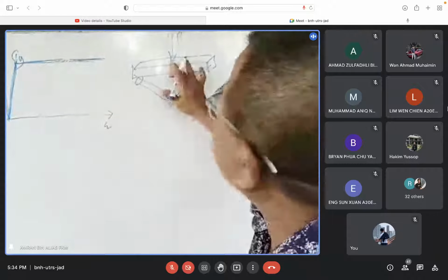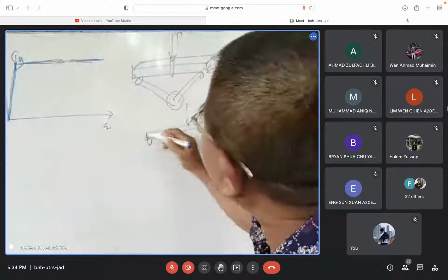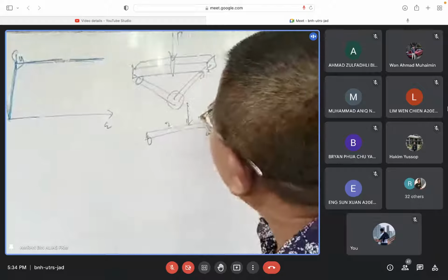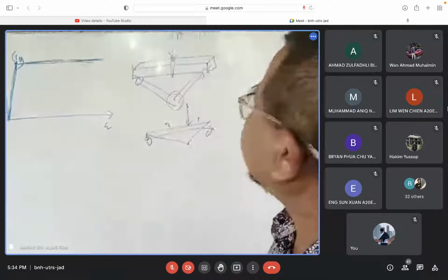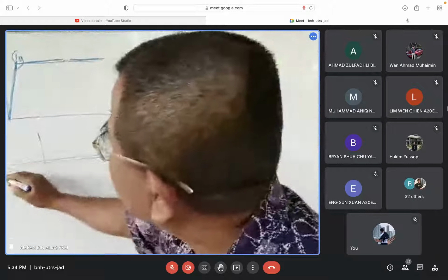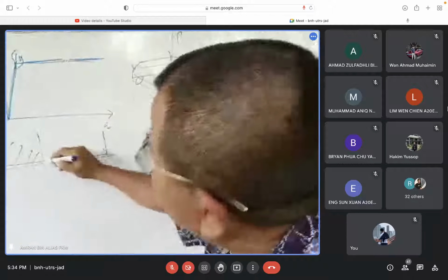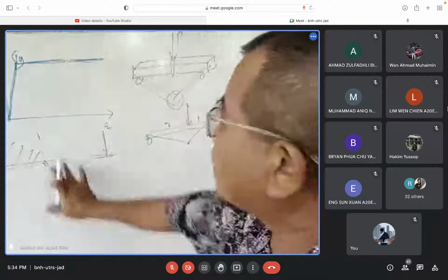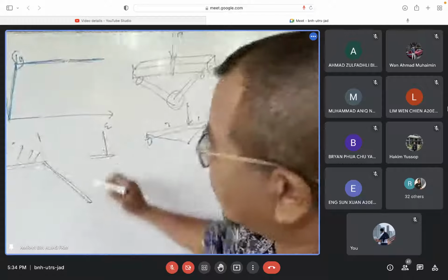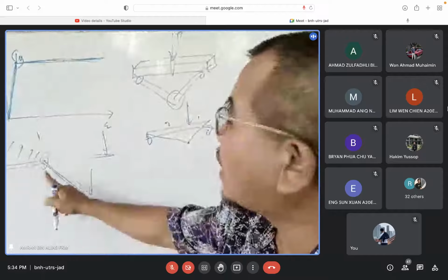Sometimes this point here is not in the middle, somewhere there, maybe 2 meters, 1 meter. So the bending is like that. Sometimes we put it built in there, push load there. So it bends like that. So the bending happens there, because those are the highest moment.